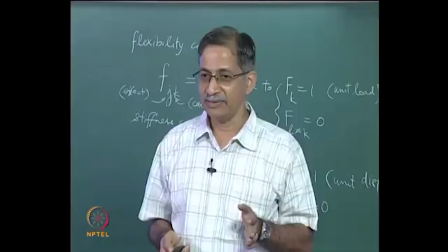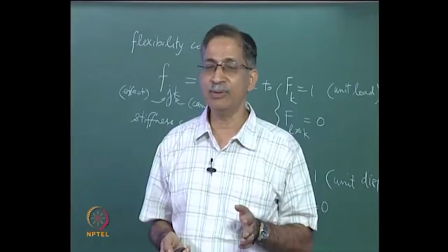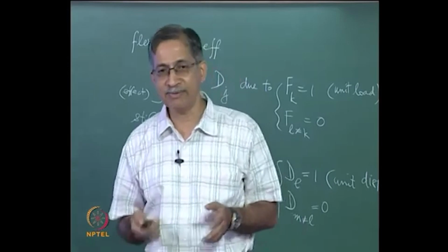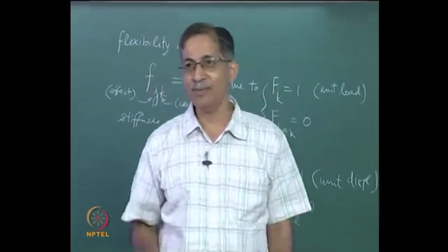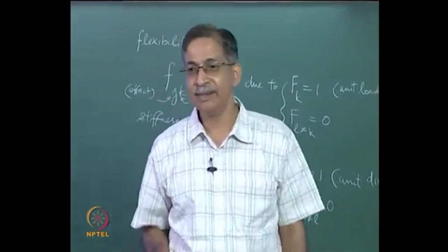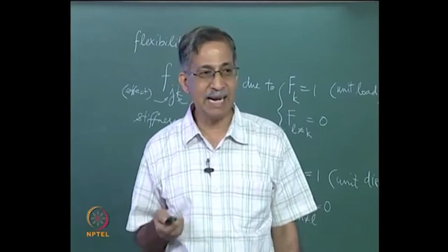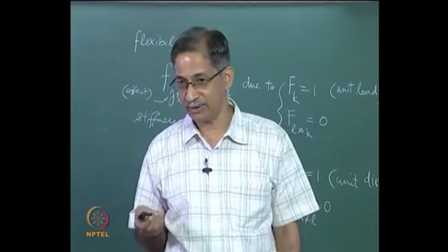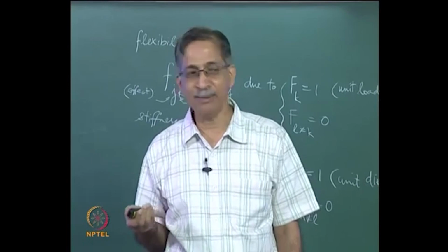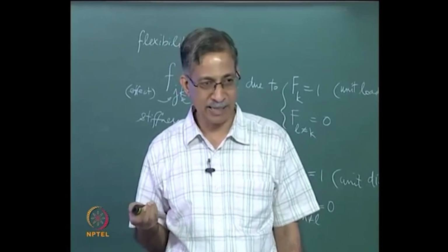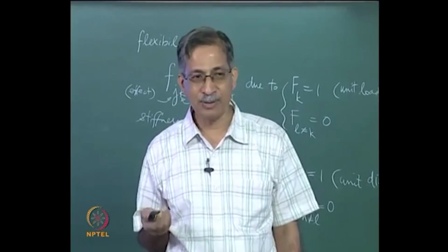You apply a force. What we have here is a real displacement field. If you divide M by EI, you've got the curvature diagram. What you need to do is apply a virtual force. This is what you should do. This is what everybody does. But there's a problem with this. The problem is you again are dealing with a statically indeterminate structure, and you need to spend some time to figure out the small m diagram for this. Is there a way out which is easier?